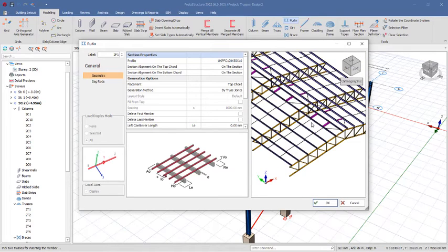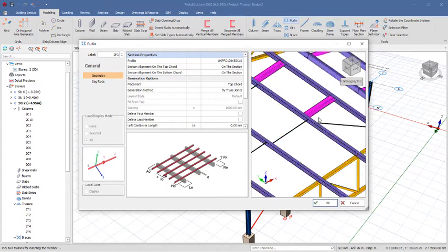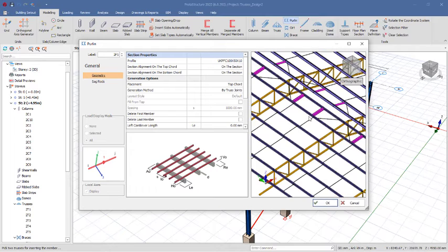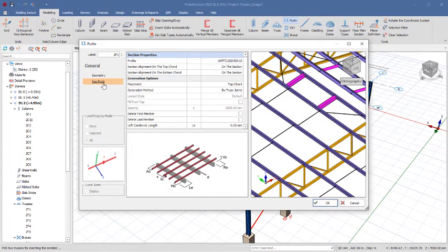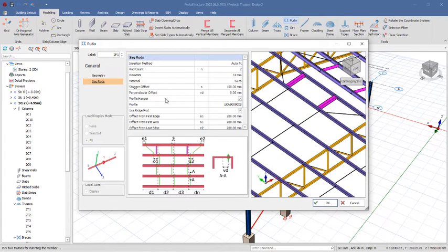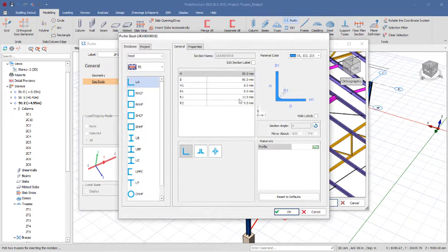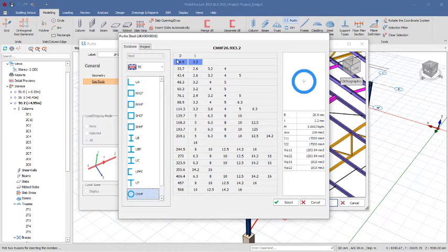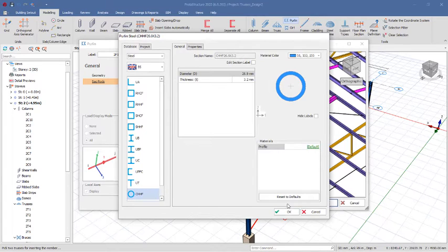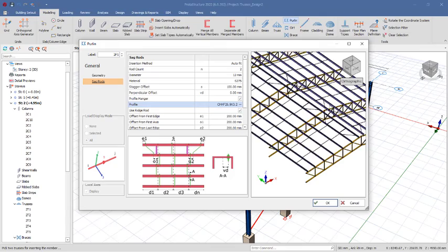Okay. So for the purlins, you will notice that we are having an angle iron for the bracing rod. Okay. So we'll go to the sag rod right there. We really want to use an angle iron, so we change the profile from a universal angle to, or maybe we'll be using pipe, this one. So we select the least one, which is 26.9 by 3.2 thickness. Alright, click on the select option and OK option to have this just like this.